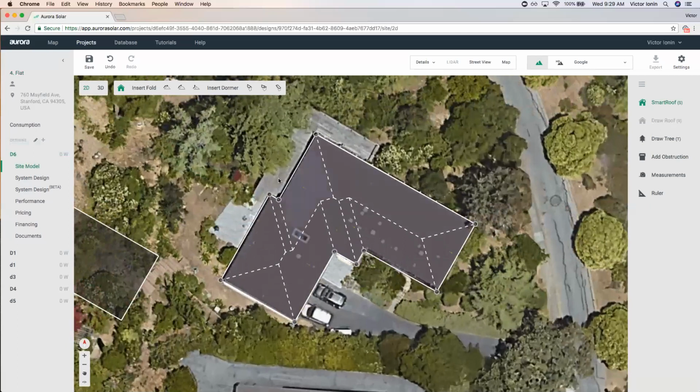No matter which option you select, you need to exit this draw edit mode. You'll notice right here, there's a menu at the top. I'm currently in the draw edit mode, and I can click on each individual item. I need to exit that. So I can either hit escape or double left click anywhere outside of this structure. That's going to help me exit the mode. You'll notice the menu is gone when you exit the mode.